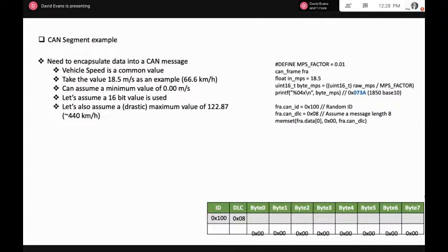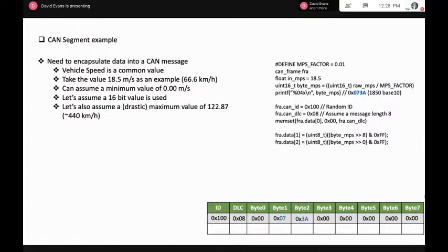We're going to clear our entire payload, because at this moment our frame data value is not set to anything. Just to make sure everything in those values is effectively what we set it. We don't want some random values going in there from unset elements of an array. And then we're going to take our value. So I think it's the 07. We're going to take the upper byte and stick it into byte 1, and then stick the second part of that into byte 2.